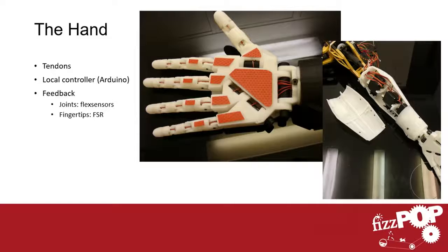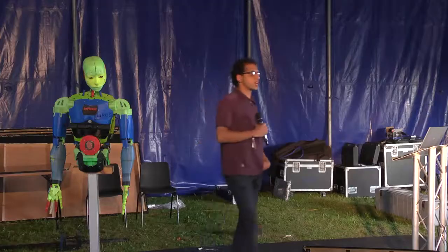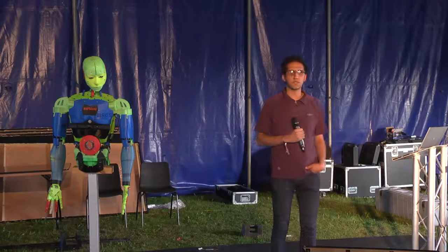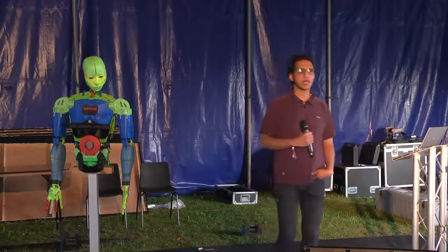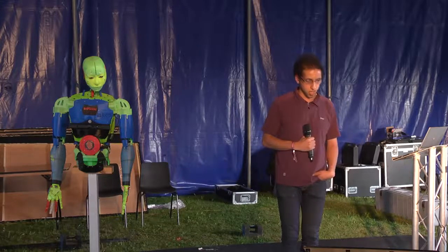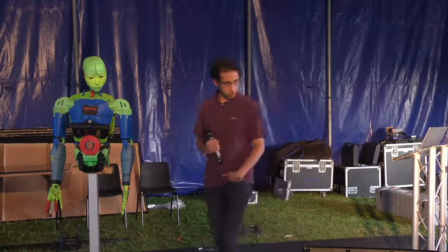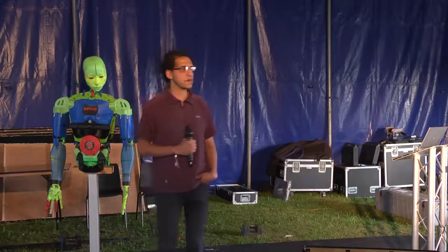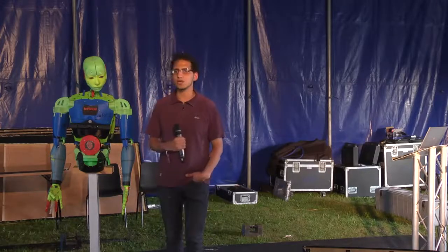The first problem I came across when I did that is that the tendons would scratch against the corners of the different parts of the hand, and they will get ripped apart. Sadly, I don't have a photo to explain that, but the solution I found is that you can run the tendon inside a tube.